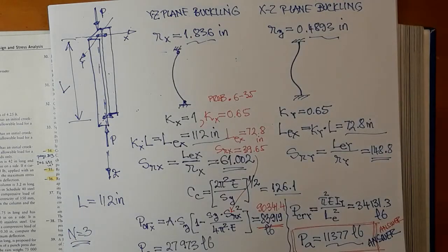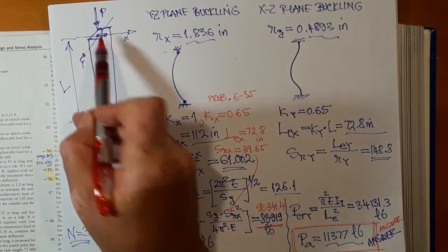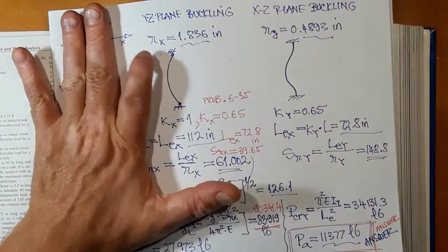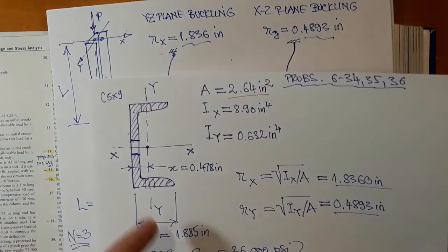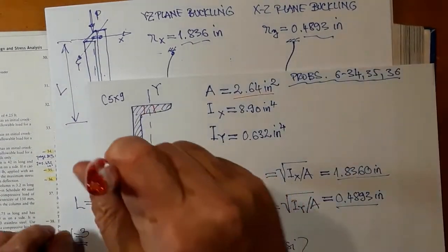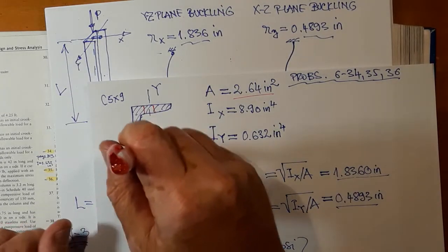So it's a better approach to drill the hole as shown if there is a need to pin the ends. Drilling the hole here is a better approach than this one, provided that you can, again, deliver the load axially and not over the whole area.